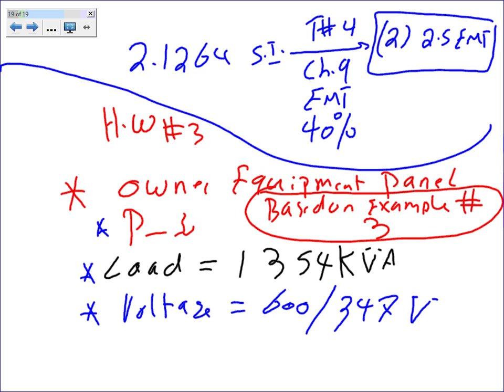Normally we give the type of the conduit, but why don't you decide the type of the conduit this time? Use your imagination, Mr. Webb. And decide how many you're going to run in parallel. You're a designer now. You have some freedom. Let me just give you guys a hint. If you're inside a building, EMT is the most common one, and THHN is the most common one. So if I were you, probably THHN and EMT.